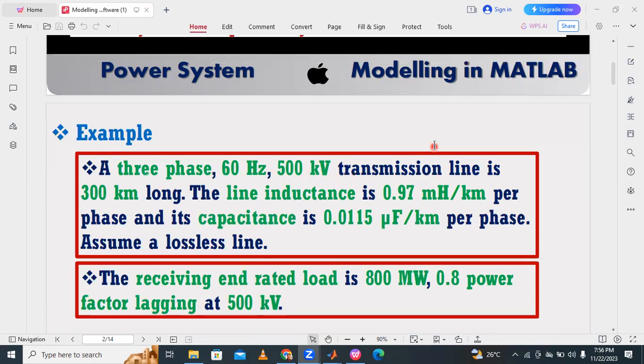Coming to the example, here is a three-phase 60 Hz 500 kV transmission line, 300 kilometers long. A long transmission line is approximately greater than 160 kilometers. The line inductance is 0.97 millihenry per kilometer per phase, and its capacitance is 0.0115 microfarads per kilometer per phase. Assume a lossless line, that is, resistance is 0.